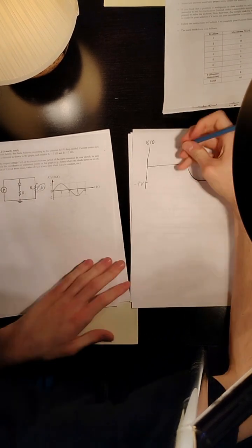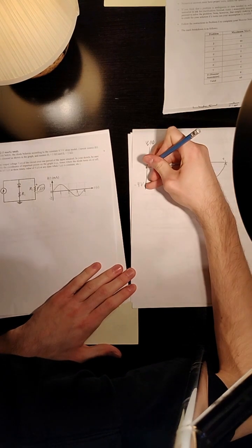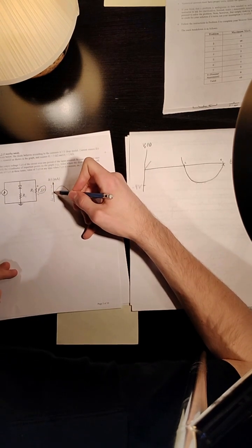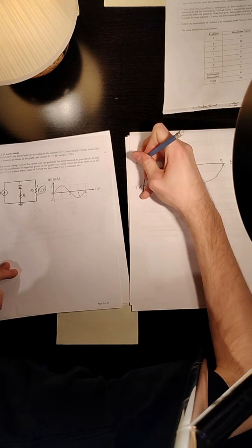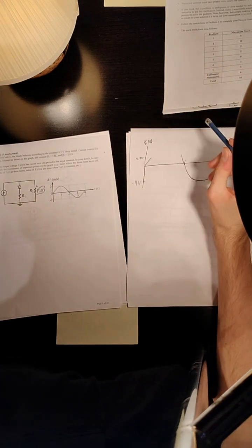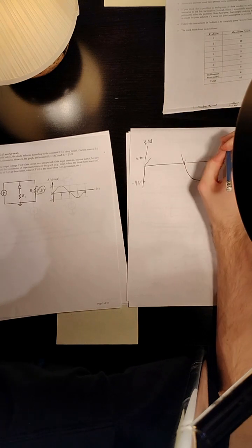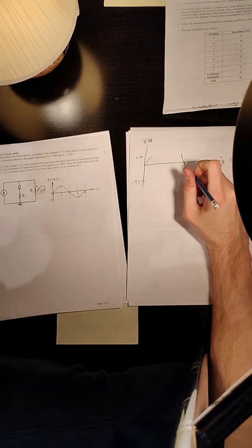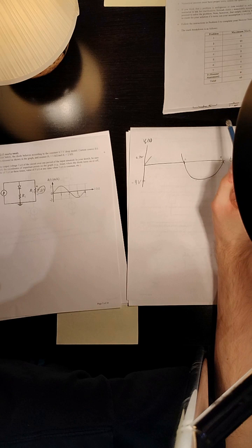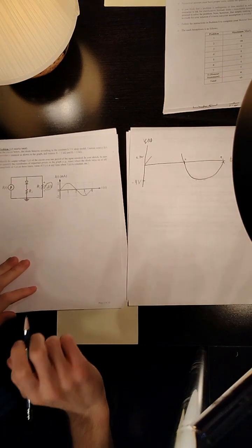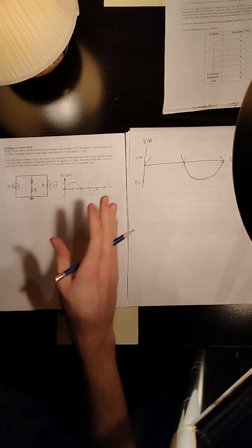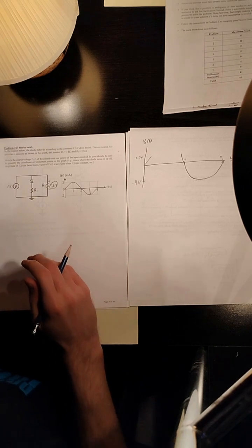Now, you can imagine that the sinusoid would continue to behave this way, even on the positive side, until VO of t reached 0.7 volts. Then suddenly the current has two different ways to go. So, at this point, I think I'm going to start needing some equations. And that would be my recommendation for any problem on the exam. If you're not really sure where to go next, spam equations and see if you can get something going.